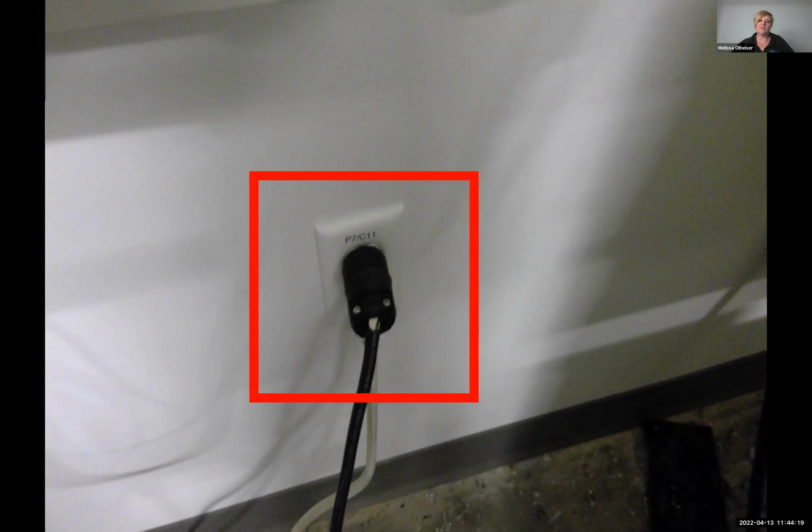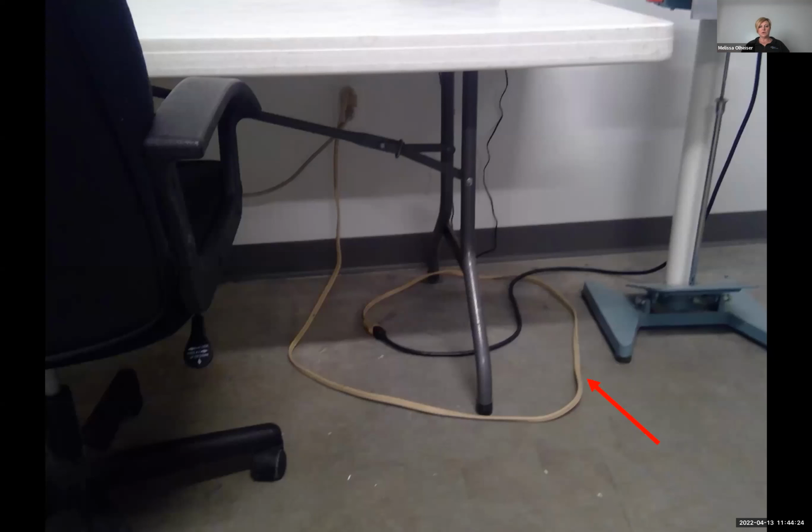But that again, it becomes, have we trained them? Do they know to inspect equipment prior to use? The next one with the cord. So this is, I feel, pretty behavioral. That piece of equipment could have very easily been plugged right directly into the wall. They didn't need to have an extension cord, but the flat ribbon cord is also not rated for industrial use. So depending on where this is, we look at getting an extension cord that is rated. And the second thing is, are we using that extension cord then as permanent wiring? Because we know that that is also something we can't do. We've got to make sure that it's plugged directly into a wall.